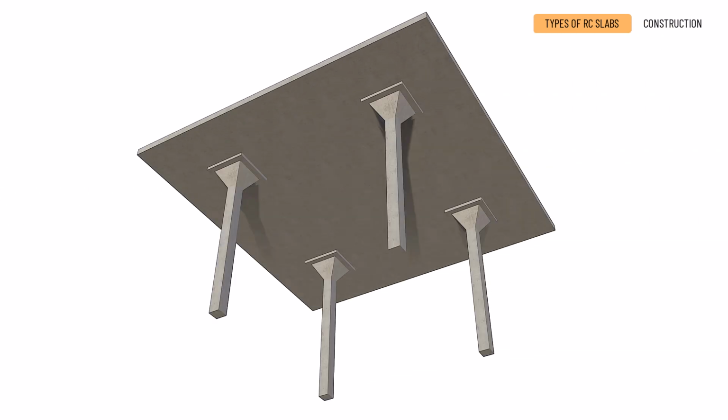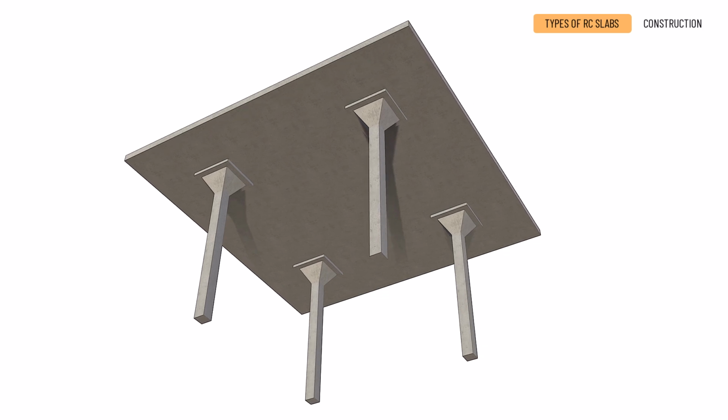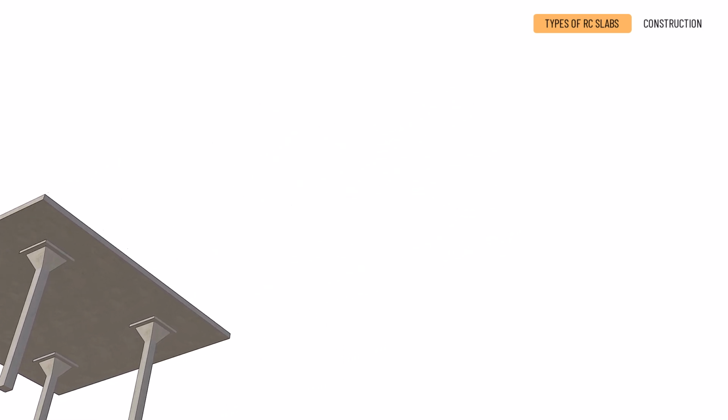Mushroom flat slabs. Mushroom flat slabs are flat, reinforced concrete slabs with two-way load-bearing and point-like concentrated supports. The connection of the pillars is achieved by means of a cone-like mushroom capital. The slab thickness is at least 15 centimeters due to the two-way main iron inserts and the reinforcing iron around the supports. The more modern versions of the mushroom flat slabs have hidden capitals,